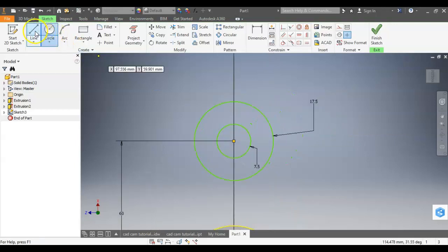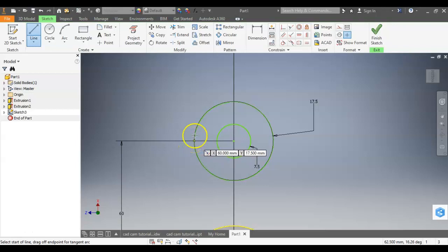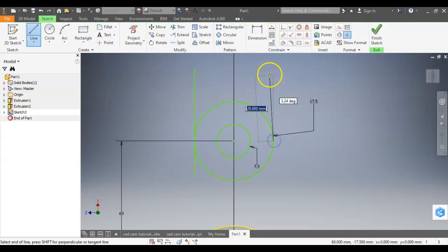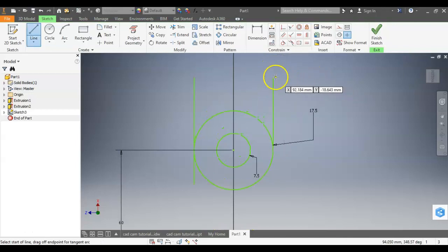So we're going to draw straight lines up. So what we can do is find this point here, or an even easier thing is just draw straight up and down lines and then use this tangent right here to tangent it to this outside circle. Okay, I'll do the other method over here. So it finds the midpoints, just like that. I tap L to complete the line there.